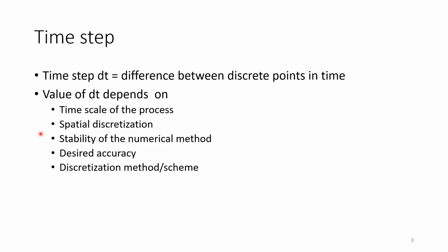All right. Then we also have, connected with those, that spatial discretization and time step are linked by stability. The stability of the numerical method you're choosing will have an influence on the maximum possible time step of your numerical simulation to keep the simulation stable. Also accuracy depends again on the physical processes, and on your numerical method, of course.